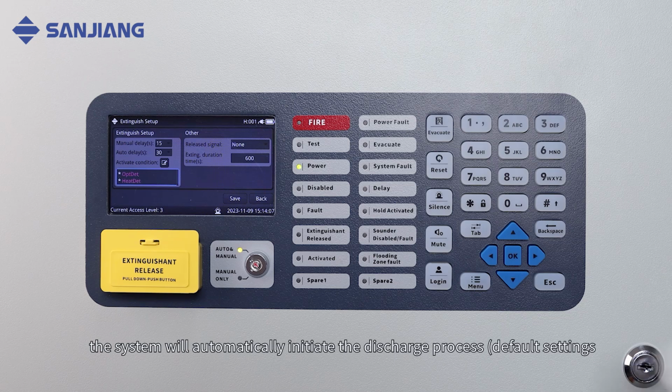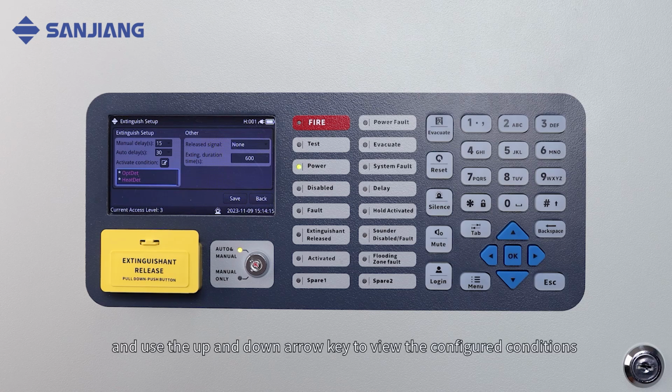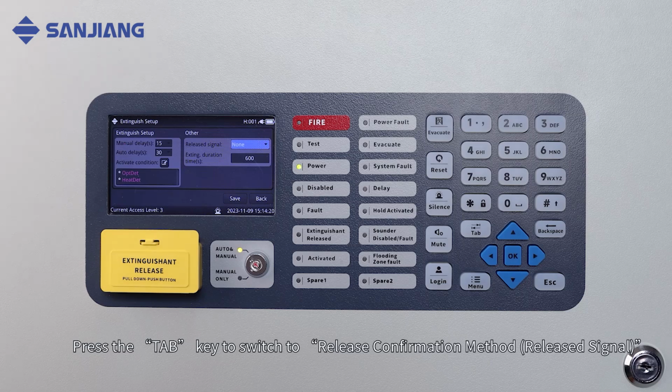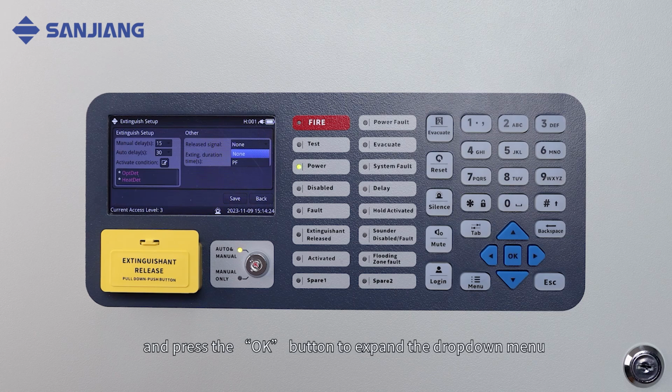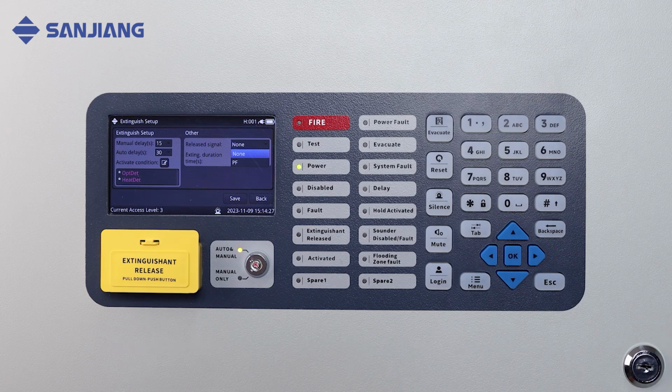When a fire alarm is reported with at least 2 of the specified device types, the system will automatically initiate the discharge process. To preview the conditions you've set, there is a preview window available. Simply move the focus to the preview window and use the up and down arrow key to view the configured conditions. Press the Tab key to switch to Release Confirmation method, and press the OK button to expand the drop-down menu.